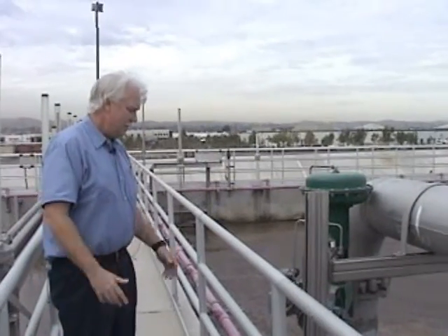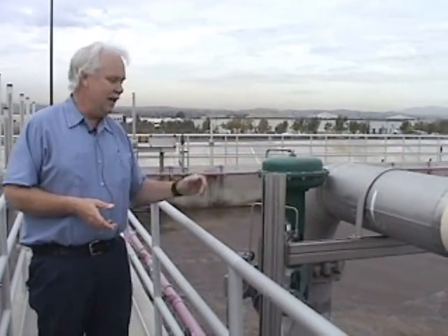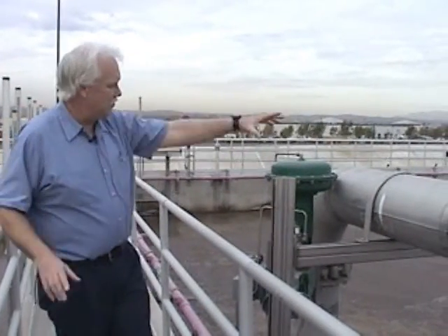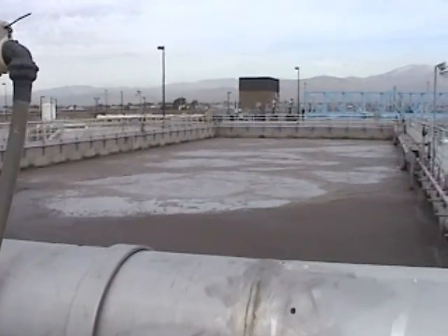So getting the Ingersoll Rand air compressor up and running is really important to get air back into the aeration basins. So in a power outage, a couple things you want to do is make sure that these valves are operating correctly, and that means they have to have air fed to them and that the blowers are restarted. Because the combination of the blowers producing the air and these valves being open allows us to aerate the mixed liquor.